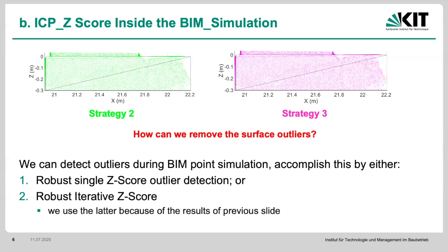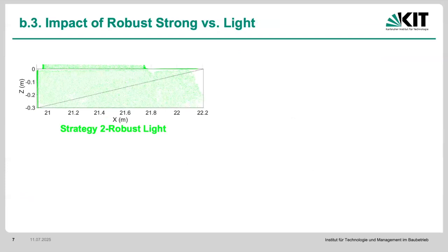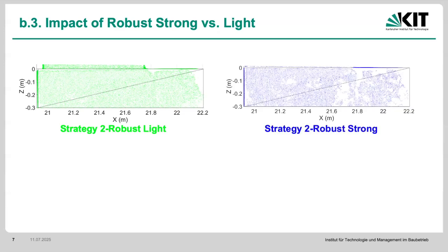Okay, so this is basically what we're going to be performing. So I called this first strategy, which is doing it one time, robust light, and if we do it in a concentration step, I call it robust strong. And this basically here, as you can see, removes all of these other ones, because every time it's basically iterating it and removing more and more and more outliers until no more outliers are removed, or until the RMSE, or the root mean squared error between 2 iterations, remains very negligible, the difference between that, right? And that negligible, if we have metric scale, I'm emphasizing on that in terms of the engineering, could be, let's say, 0.01 millimeter, okay? Or 10 to the power of minus 5 meters. That could be sufficient, okay?